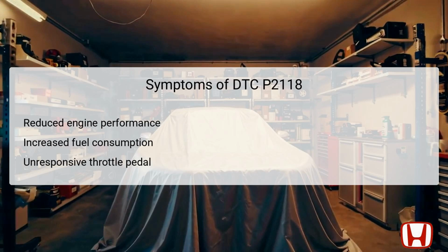Symptoms associated with DTC P2118 can greatly affect vehicle operation. A noticeable reduction in engine performance is common, as the throttle actuator may fail to respond adequately to driver input. This can lead to sluggish acceleration or difficulties maintaining speed, making the driving experience less than optimal.